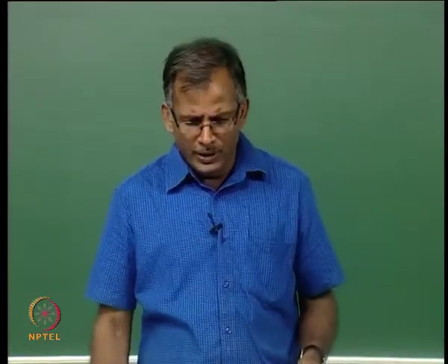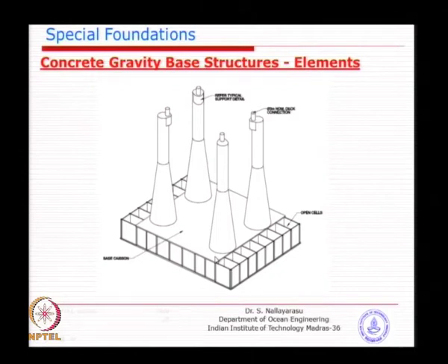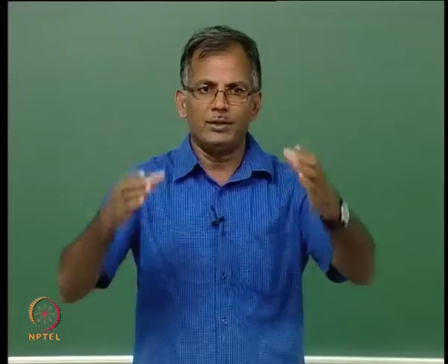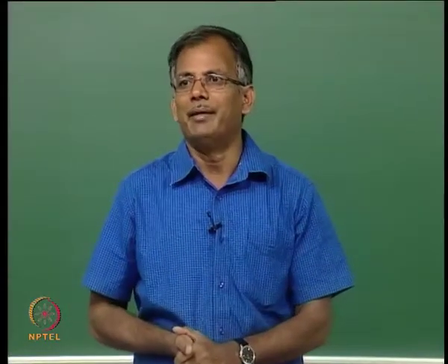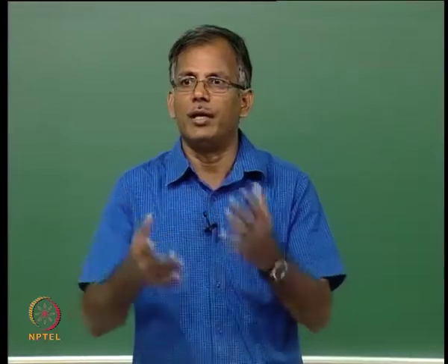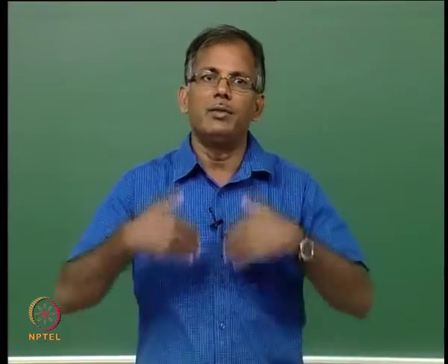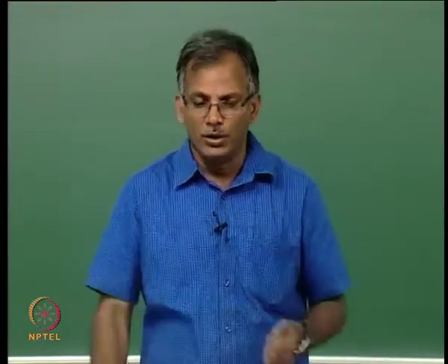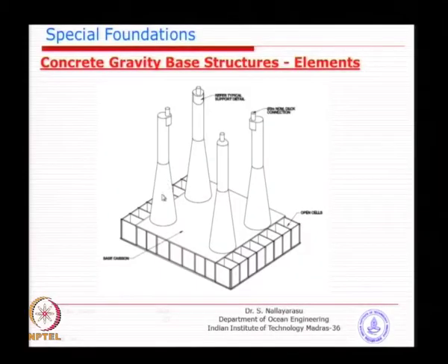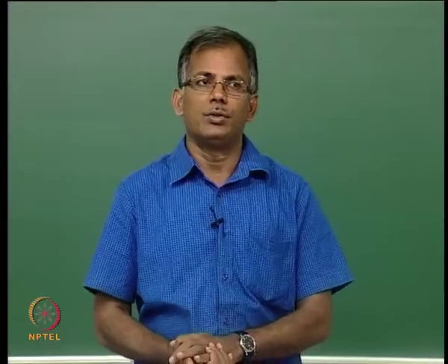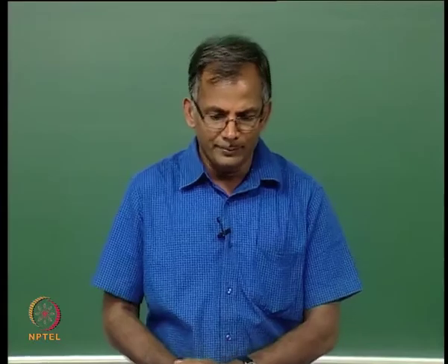At different times you will get a different buoyancy, so the weight is going to be different. For example, when the whole gravity structure is sitting on the seabed in the initial condition, no production is there, so the weight could be lower. Later, when you are ballasting and doing production, you may store oil inside the shafts, and the weight will increase on one side. So a variable loading condition can exist, and that is something that you have to evaluate.